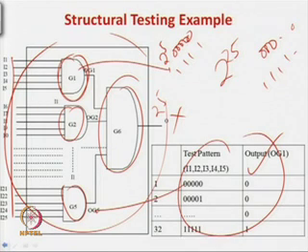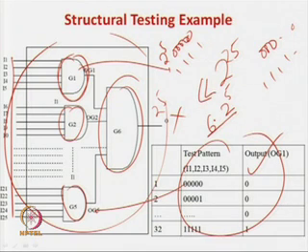So, now you can see, how many patterns do you require for this? It is very few. It is 2 to the power 5 times the number of gates, which is 1, 2, 3, 4, 5 and 6. So, this is 6 into 2 to the power 5, which is much less than 2 to the power 25. So, see what we have done.